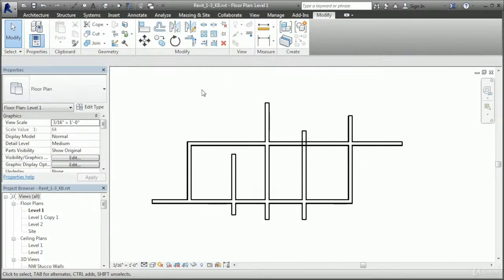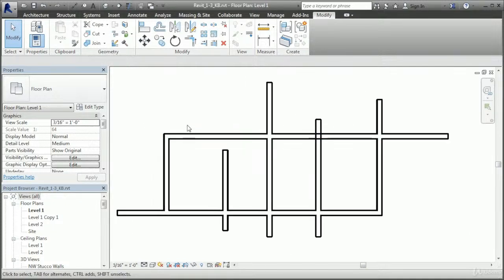It's a matter of picking a boundary and then objects that you want to extend to that boundary or trim away at that boundary. So I'm going to go to my trim extend element. I'll pick this as my boundary, and then I'll pick this one to extend up to it, and the command stops. And now I can repeat and select another boundary. I want to pick this as my boundary. I want to get rid of the piece up here and keep the bottom.